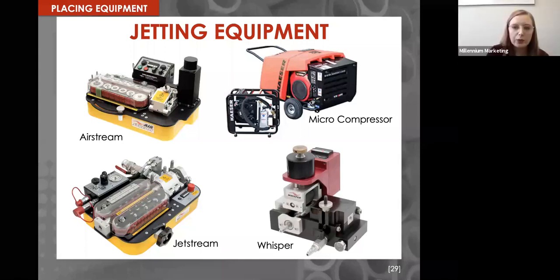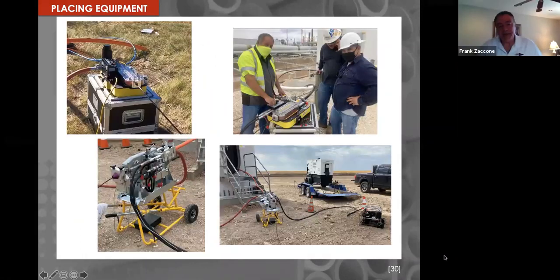Hey, Frank, we have a quick question. How far can you install microfiber with the Airstream? Well, again, it's a tough question only because there's a lot of factors involved. It depends on the compressor that you use, because the air is really what gives you the distance, plus the condition of the duct. If you have a lot of bends, they do add resistance. So every time you add resistance, it affects the performance.